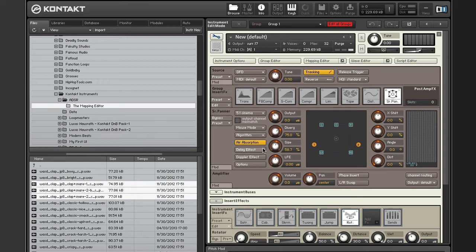Delay effect. When activated, sounds from sources which are further away from a listener will be delayed in relation to sounds nearby. Keep in mind this uses a ton of CPU. Also, if you want to simulate positioning entirely with delays and keep the levels constant, set the divergence to 0.